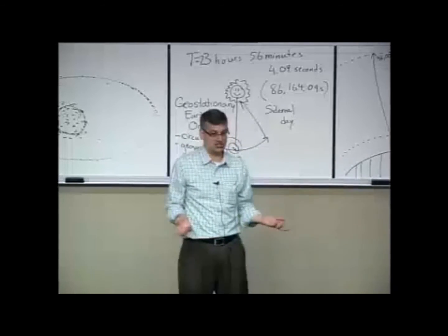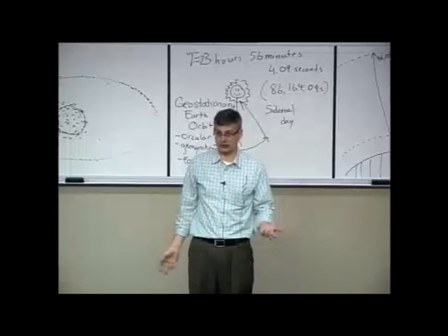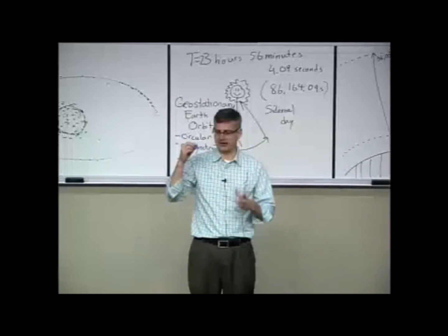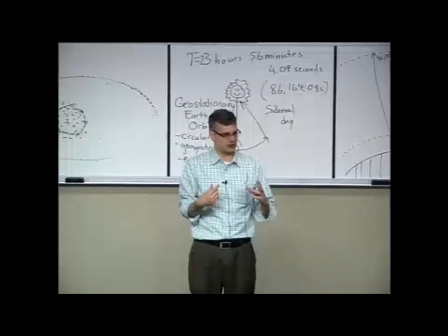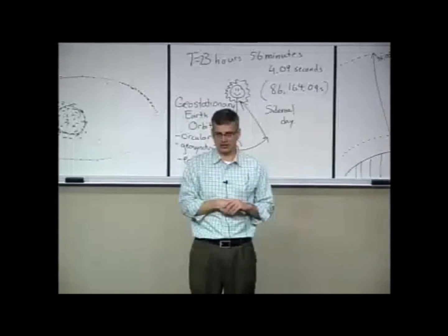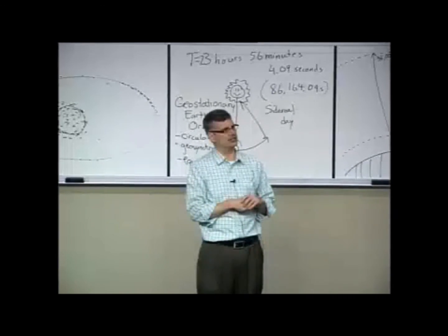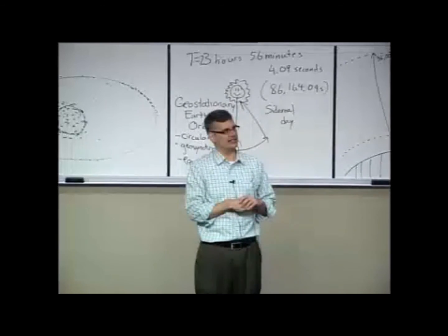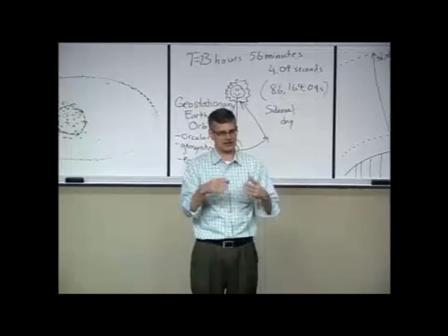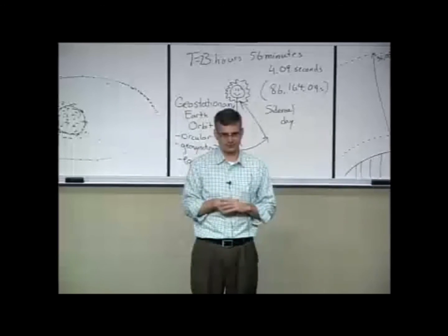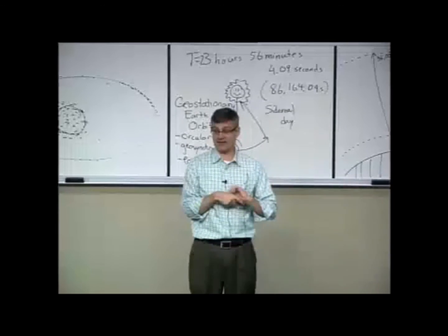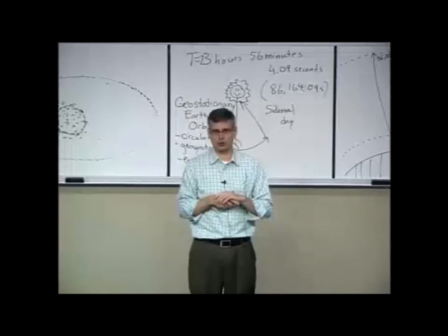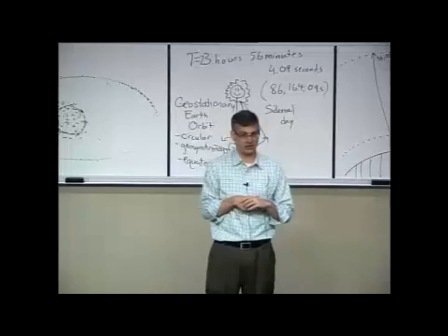Now, there are some other types of synchronous orbit. For example, there's something called a sun-synchronous orbit, which again means that the satellite may do multiple passes, but during the course of a day it will repeat itself. I forget what the exact radius is for a low Earth orbit in a sun-synchronous orbit. I don't have that example worked out in my notes, but there's a lot of different things you can synchronize an orbit to. Some are semi-synchronous. They repeat themselves every half of a sidereal day. I'll show you an example later on when we study elliptical orbits of an orbit that does that.